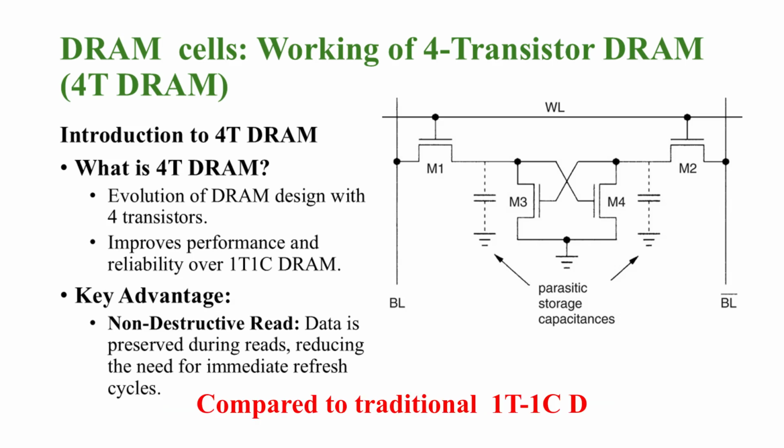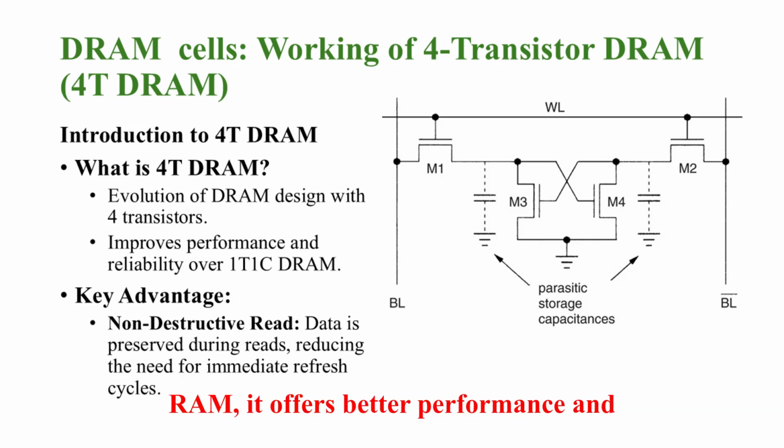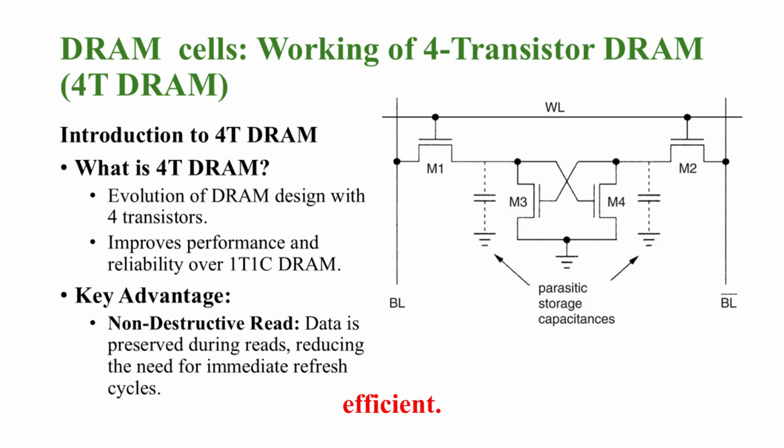Compared to traditional 1T1C DRAM, it offers better performance and reliability. One of its standout features is the non-destructive read, which allows data to be read without altering or erasing it. This minimizes the need for immediate refresh cycles, making it more efficient.